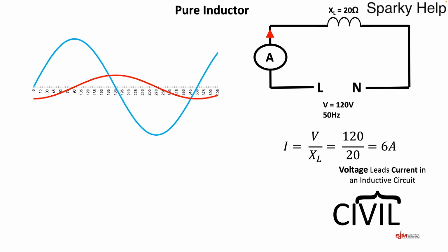So phasor diagrams are the chosen method. So what do we do? We start off with a reference line. I'm going to start with current as our reference. So remember, left to right, any length of line, and we label it I reference in this case because this is a point we're measuring from. It goes in an anti-clockwise direction. So this is a rotational line effectively, but we've got it at a point in time. It's rotating by 2 pi f or omega.